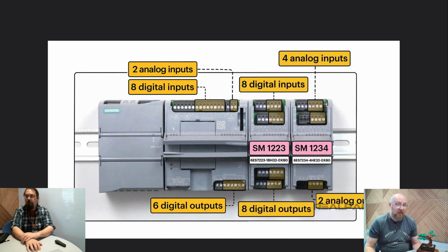Yeah. Like if you have one that says L1, L2, and then the L2 has a neutral underneath it, you need to be aware that's going to be different. You need to go and look into the documentation and understand what they mean by that, because the manual is going to be for multiple different model numbers. You need to check what it means for your model number. Exactly. And again, that's something we've got to watch out for.